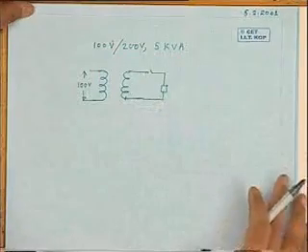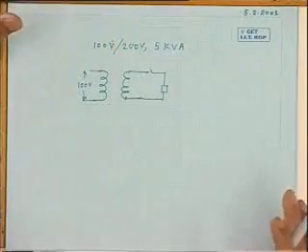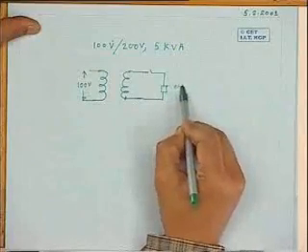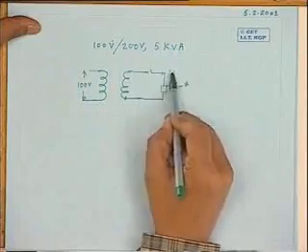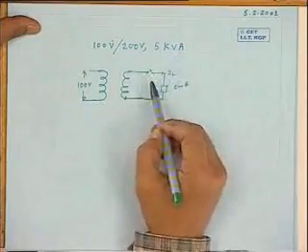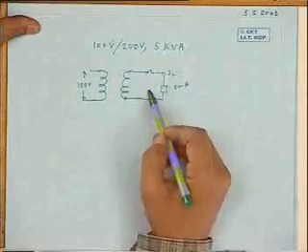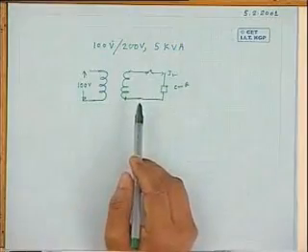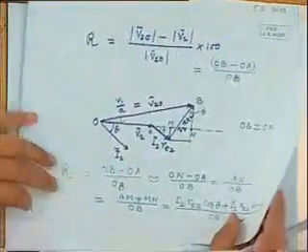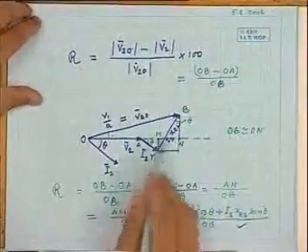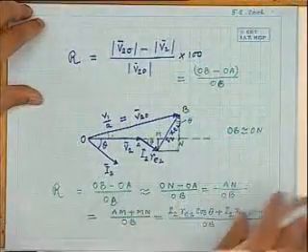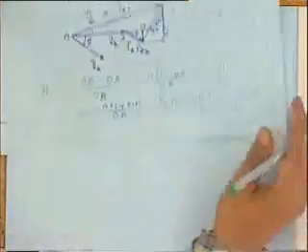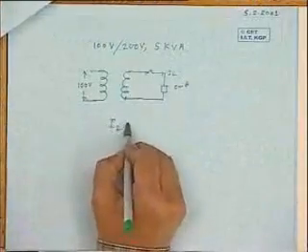Now the transformer is loaded. One kind of problem, which is quite natural to ask, is that suppose this load description is known, power factor I know, how much current it is drawing I know, then if I close this one, how much will be the magnitude of the voltage? So I can easily calculate by what formula? Not straight away the regulation formula. You should remember that this OB minus OA is the difference of this voltage.